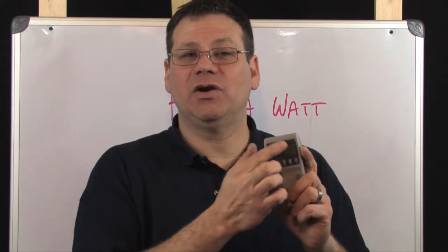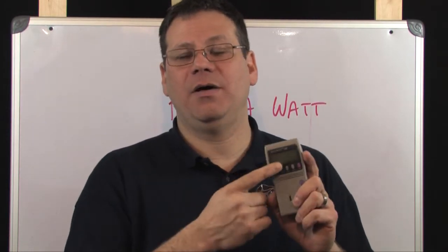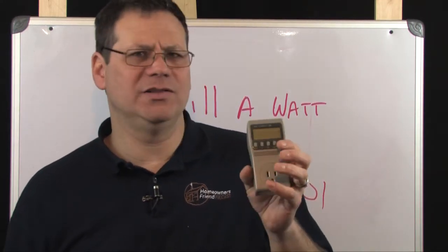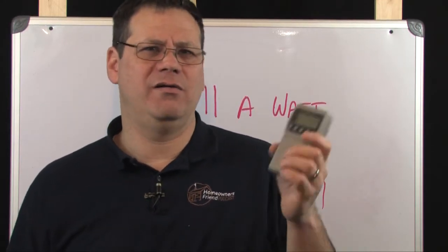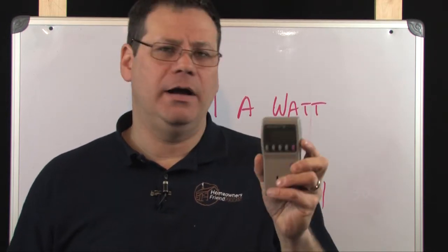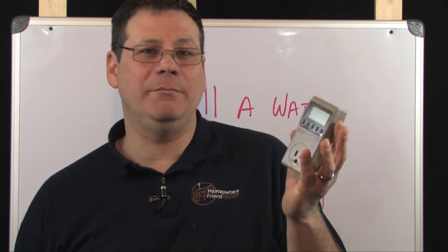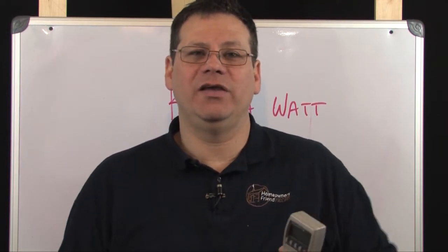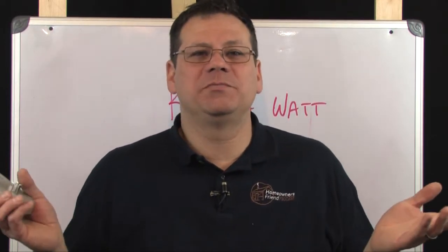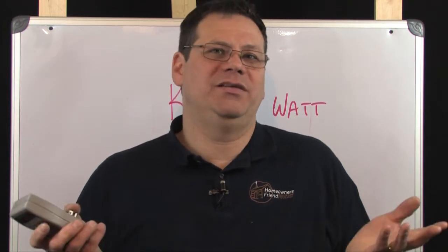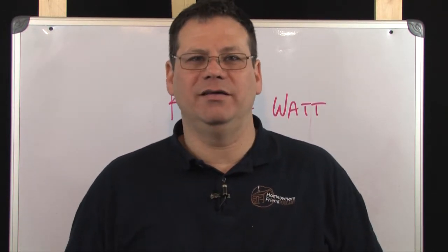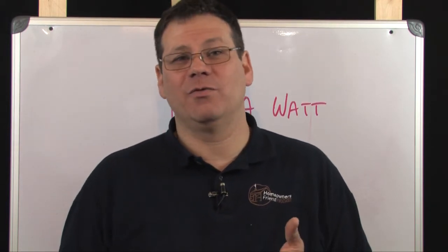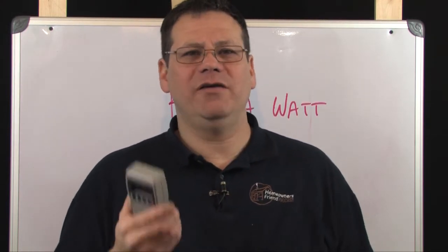And it also tells you how much it costs to run it for that day by automatically multiplying by the cost factor that you put into it. And I think it'll do it for a day, a month, a year or something. There's some different options. But really cool and very simple to do, and it's great for devices where, again, a light bulb's pretty easy to calculate, right? You just need to know how many hours it runs and the wattage. But the refrigerator, you don't really know how much it draws, and you don't really know how often it runs. This is great for a refrigerator.